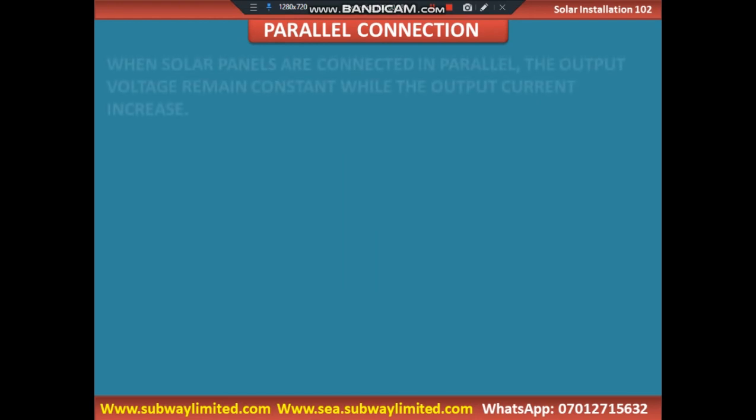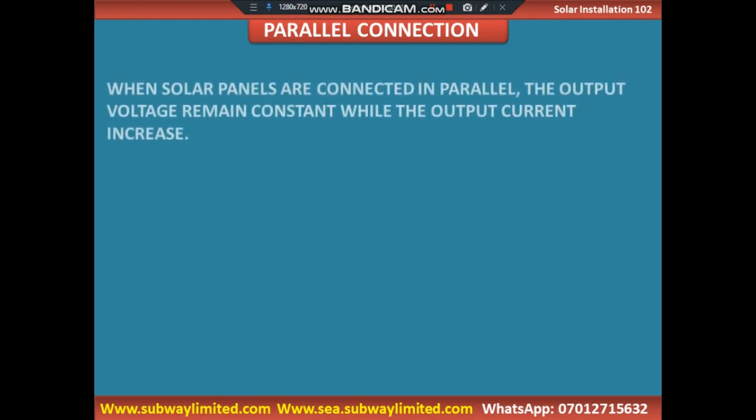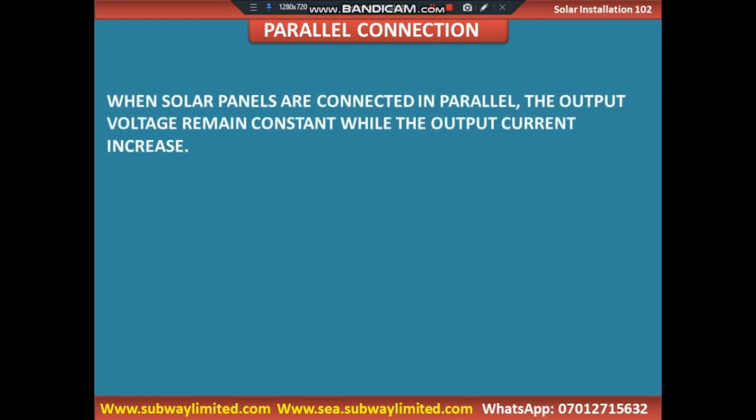Here we are talking about parallel connection, and we are telling you that when solar panels are connected in parallel, the output voltage remains constant. Remember, when we were talking about series connection, the output current was what remained constant, whereas the voltage increases. But in parallel connection, the output voltage will remain constant, while the output current will increase.